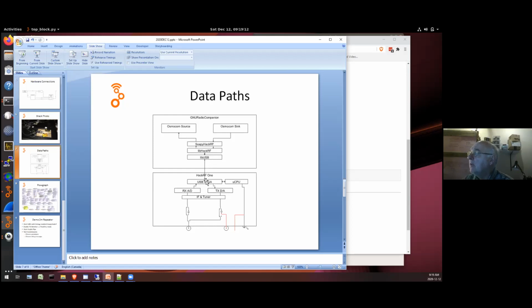Inside the HackRF One, there's actually an FPGA, which is a Field Programmable Gate Array. It handles the USB interface and splits the signal so that when we're streaming in receive, we're getting a stream of floating point numbers at whatever sample rate we're using. I'm using 2 megasamples per second. And it switches that when it's in transmit mode. Samples go the other way, out to the D to A. There's a bunch of RF circuitry in there.